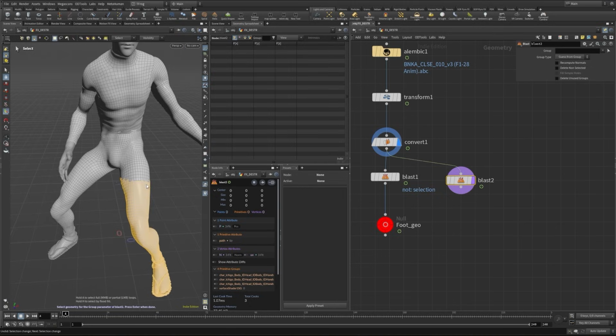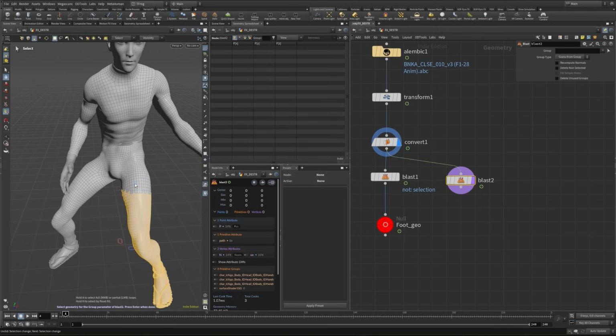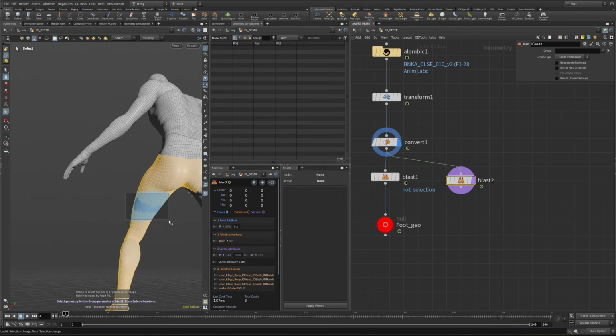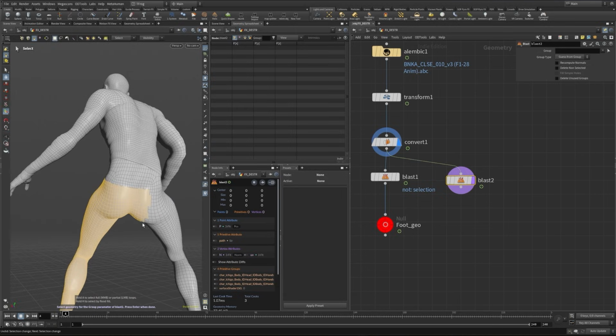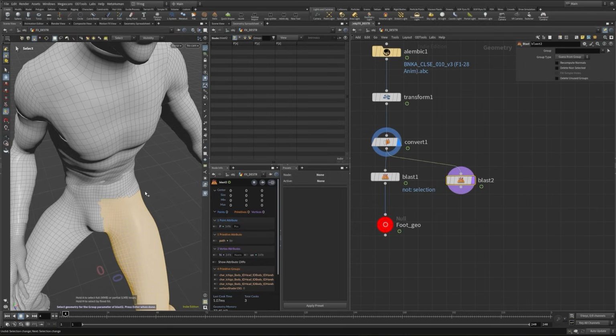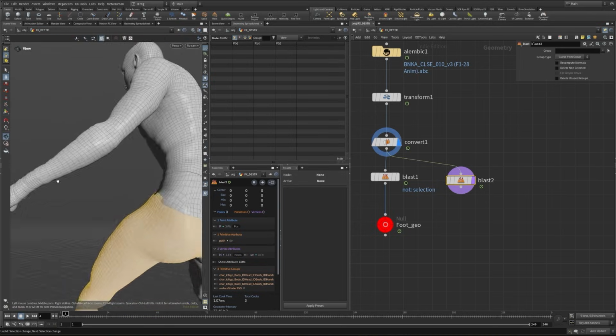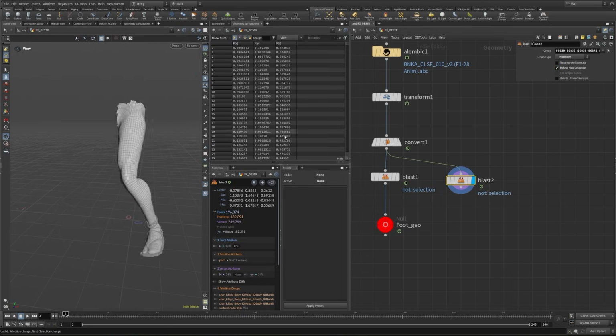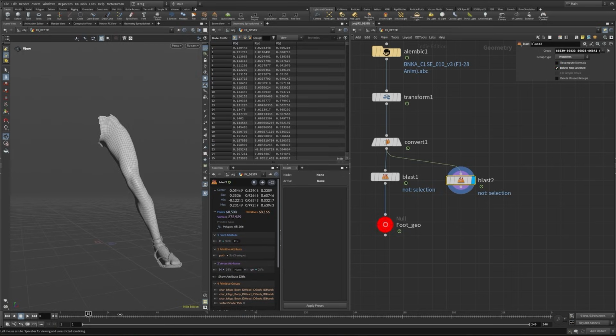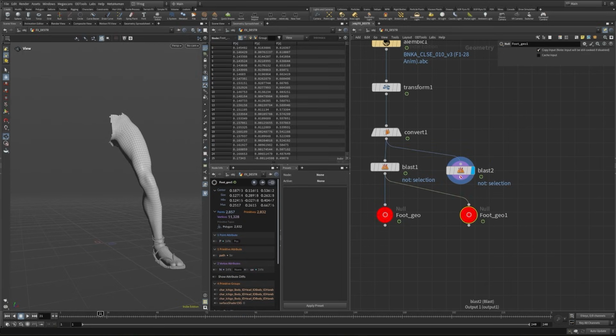So there's sometimes this issue, so make sure you only have this box icon here selected. If you have something selected over here, you can select even more with holding down shift and then select more, like so. And over here, I also want to select this part. And if you want to deselect something, you can hold Control and deselect this part here, for example. So we really only get this leg here over here. Now let's press enter and delete non-selected. And we only got this leg here, even with the animation. Now let's plug this over here. And we will call it character geo, like so.